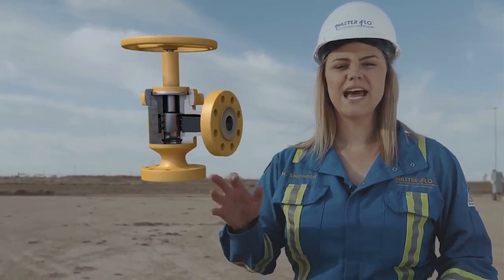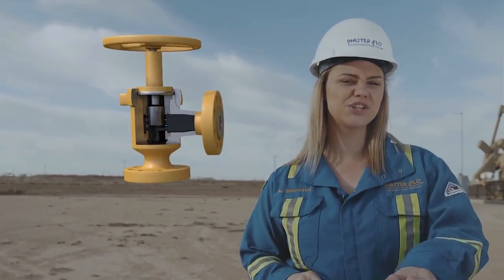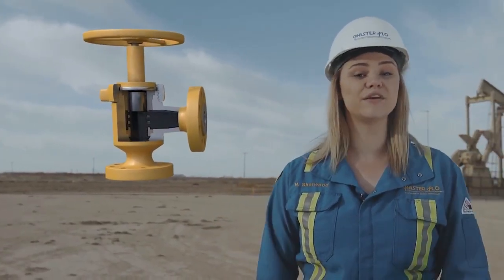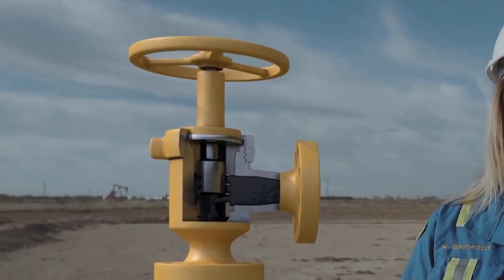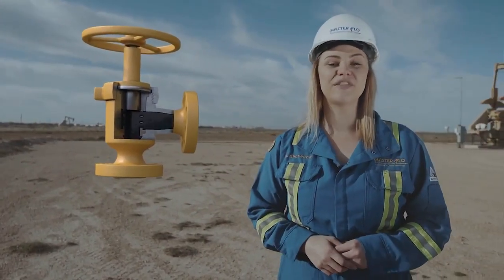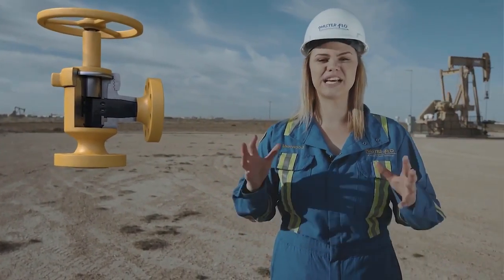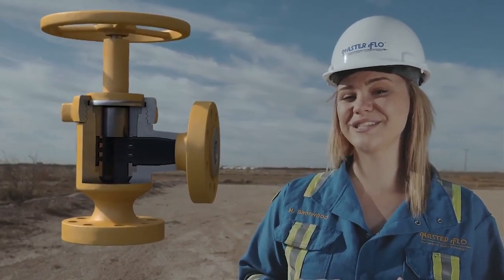Our next choke valve has a fixed cage and internal plug. A stem connected to the cage allows the cage to be moved up and down by the rotation of the wheel, changing the size of the opening for the flow. Inside the choke, fluid circulates in the annulus between the body and the cage. The location of the cage openings forces the streams to collide in the middle. Impinging streams cause hydrostatic back pressure and allow using fluid energy against itself, resulting in minimal wear of valve material.